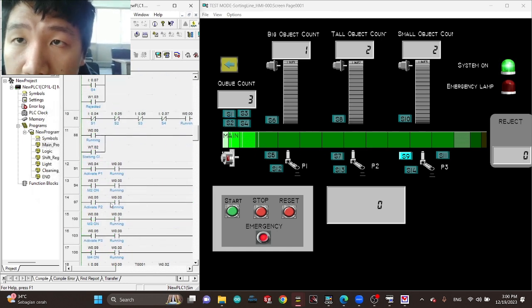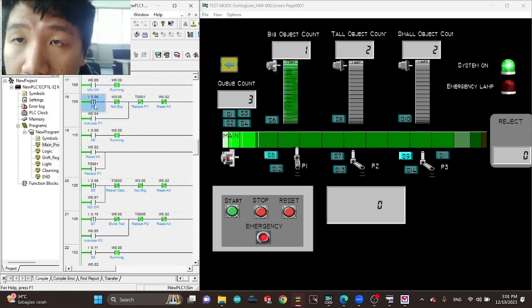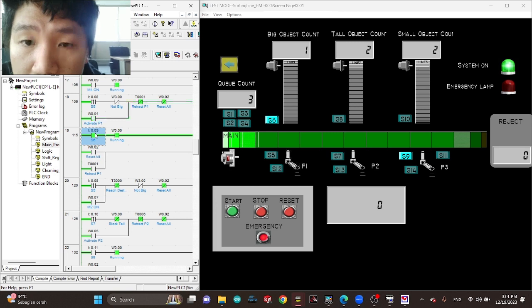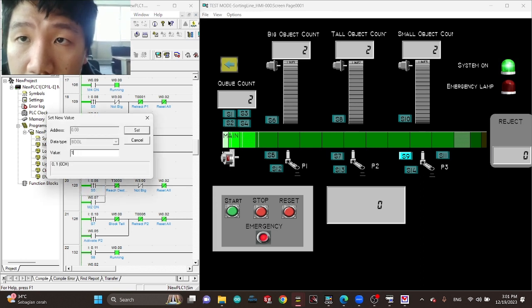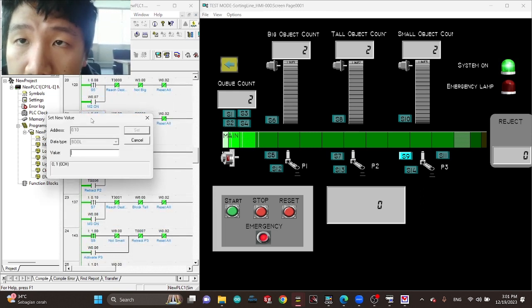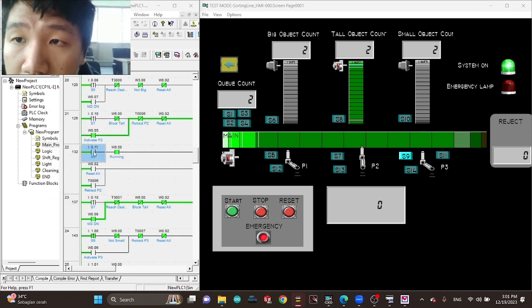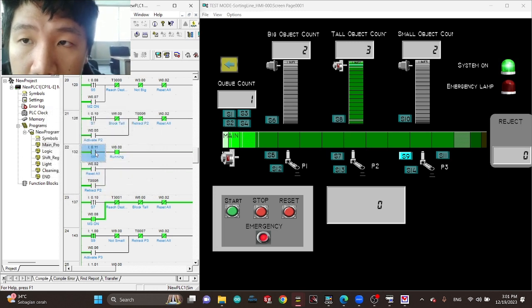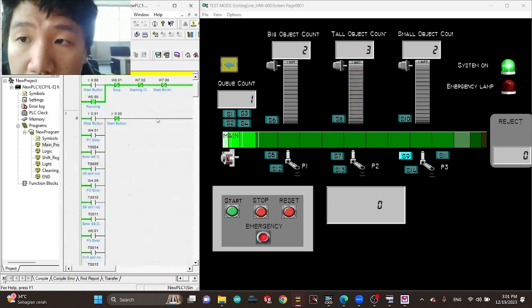There we go. So the big item is going to pass through S5, where it's going to be pushed. There we go. It's pushed. It went to S6, and then it was detected and went back, as can be seen. And then right after the big item, the previous tall item is moving to S5. It passed through S5, and it can be seen it's not being pushed, and it will go to S7, where it's going to be stored. There we go. It's pushed to S8, where it's received. It will retract P2, and by doing so, there we go. We have the item, and it turns off.